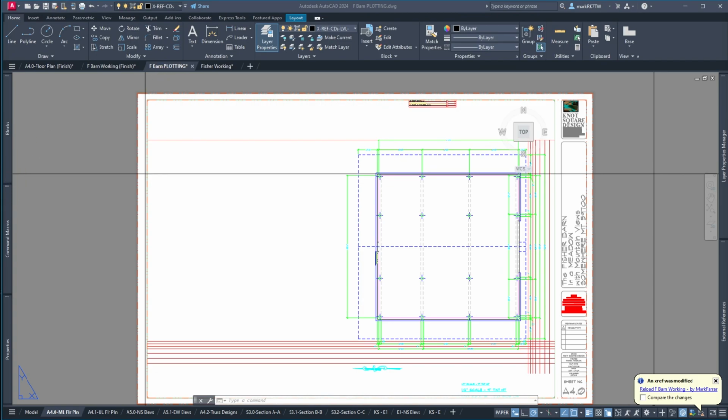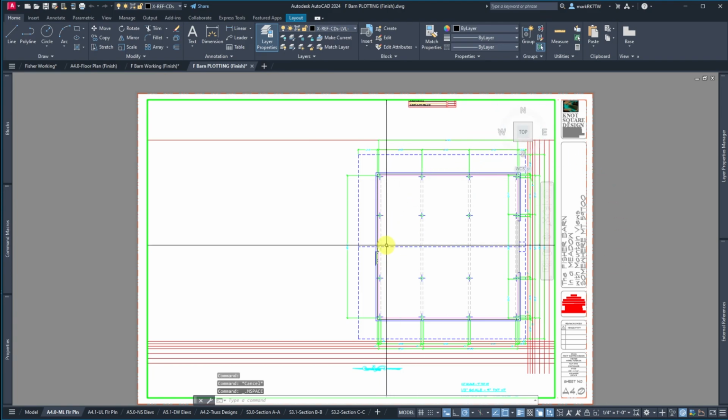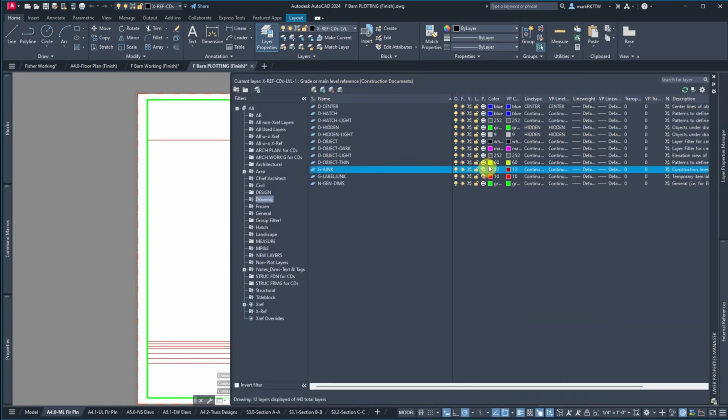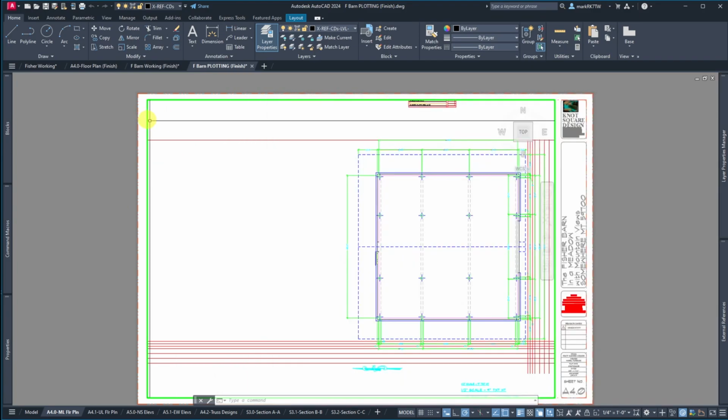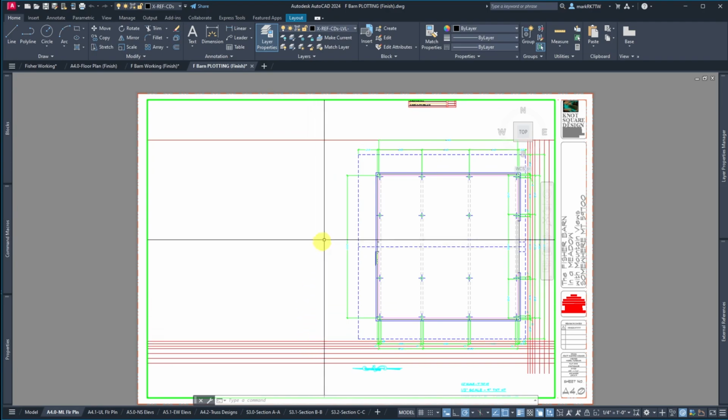And so we need to get our stuff together and take a look at where we go from here. This is kind of where we're going to end up, here in this plotting drawing to do our plots. In the viewport, I double click it, and you can see this viewport get bold. In the layer options, I've got the G junk and the G label junk layers set not to print. I can see them, and that's what these lines are here, these dark and a little bit lighter maroonish red or burnt umber, whatever you want to call it. So that's what those are, and they don't plot.